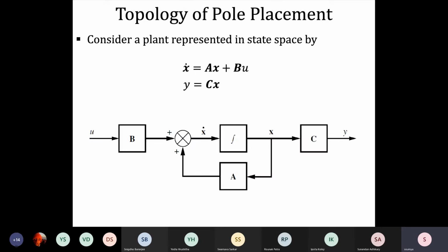Okay, so we are considering this kind of setup. You have X, which is the state variable, right? Now the differential of X depends on two things: AX plus the control input U multiplied by B. That's your system right now, and the output Y, which for us is Y equal to X. In general, Y goes through a transformation matrix C, so Y equal to CX, right? These are the equations we are assuming for the plant in its open loop.